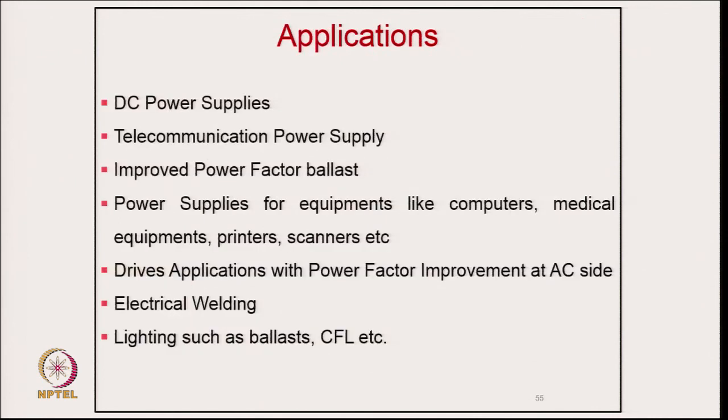So, coming to this, we can talk about the applications where it is used: DC supply, telecommunication supply, improving power quality, power factor ballast like lighting systems, power supply for equipment like computers, medical equipment, printers, scanners, and drive applications for power factor improvement on the AC side, electric welding, high frequency welding, and lighting such as CFL, LED lighting. In all these applications we use these PFC power factor correction converters.